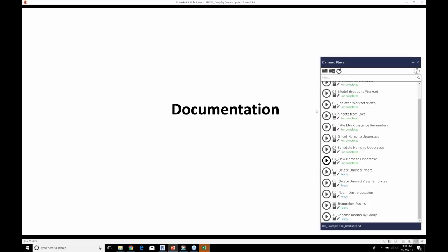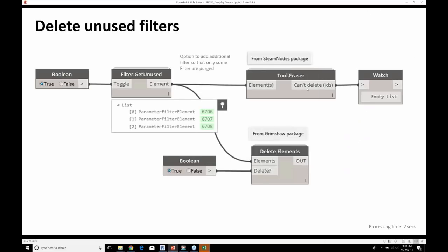So one of the things around that is deleting unused filters. This came from personal experience working with someone in a team who was really trigger happy with creating filters. We had hundreds of them, 300, 400 filters, and most of the time they weren't named very descriptively. I might say "Paul's awesome perspective view," and then "final view," or something really silly like that.